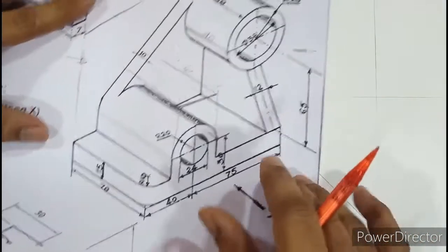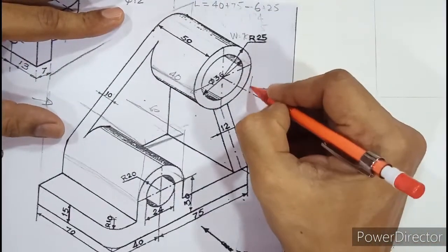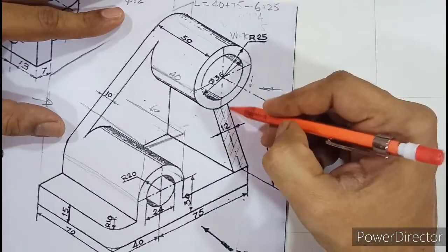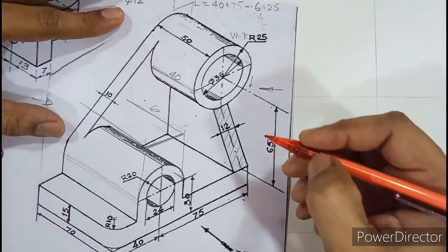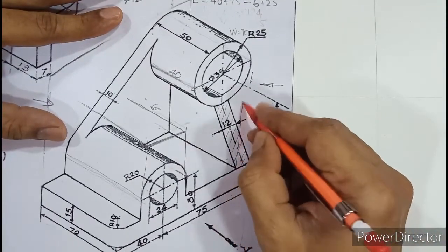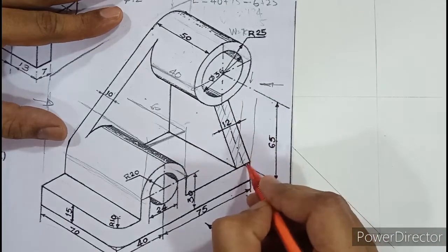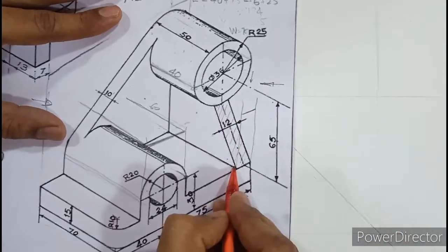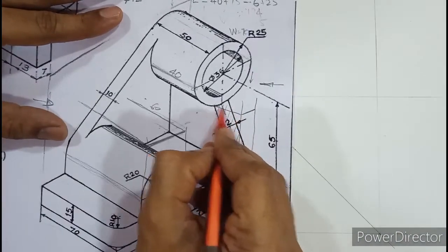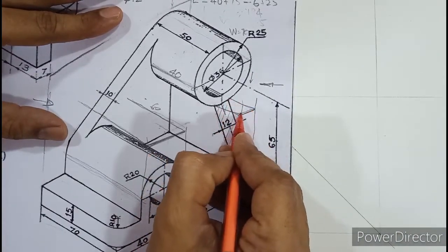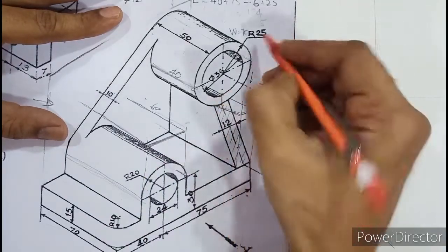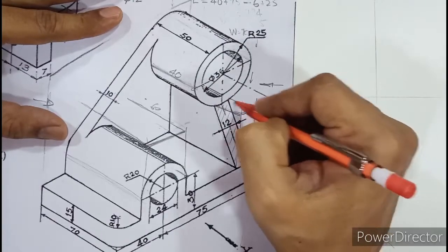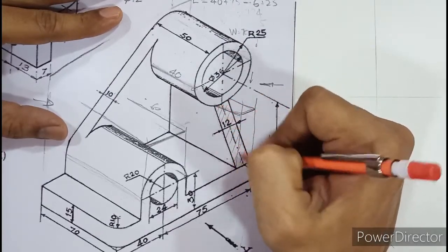Now proceeding further, the question is, in the top view, will you be able to see this inclined surface coming out? Will this 12 mm plate be seen, yes or no? So in the top view, what you do is that if you extend this line and if you extend this line, so in the top view, because this is coming out, this straight line will be seen here. Then this inclined lines will be seen apparent. So this sort of rectangle will be seen, but that of reduced size. So in the top view, beyond the cylinder, you can see 3 such lines that belongs to the rib.